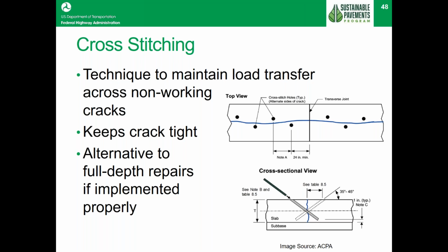But it's a way to fix a crack on an otherwise really good pavement that you want to keep. If the crack is due to loading, you would not want to do this kind of solution, as it would not work. I've done a couple of these in a few cases, and they've been pretty effective on some of the roadways.